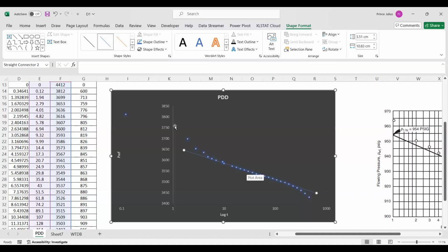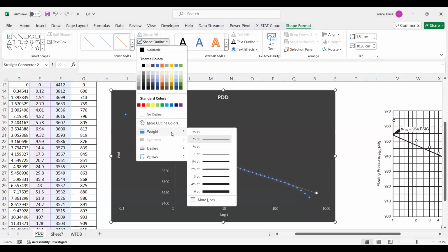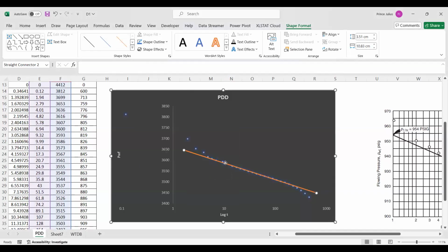Okay, so both are in blue color. It may not give you the right representation, so I will change the color. If not, I can even increase the tone of the scale a little bit. You can see the points which are falling on the scale cannot be seen. So this could be a position where the maximum points are fitting on the scale. You can consider this as my final position and extend the scale to meet your axis.